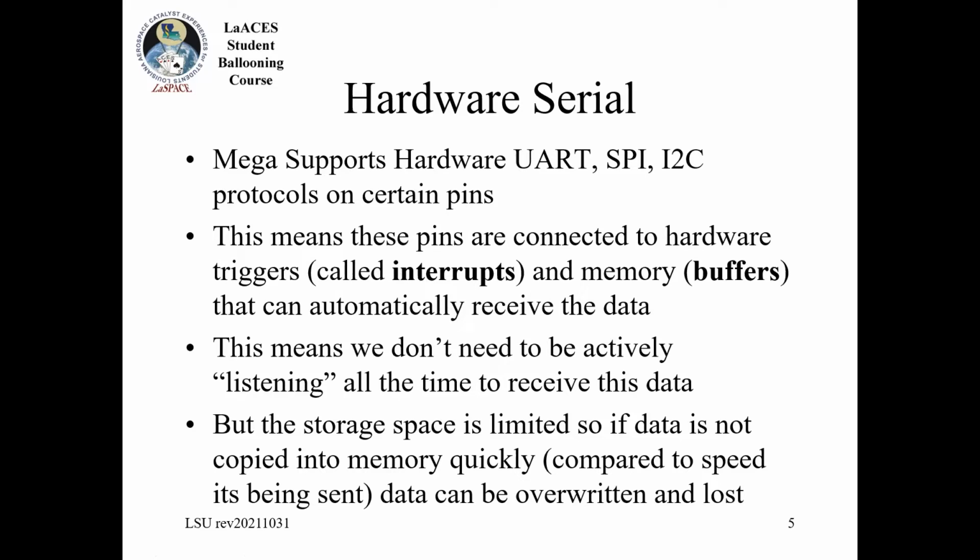That's what's called an interrupt. And then there are usually separate small bits of memory called buffers, so that the microcontroller can copy the incoming data into these temporary buffers and hold it for a little bit until your program gets a chance to go look at it and copy the data out.